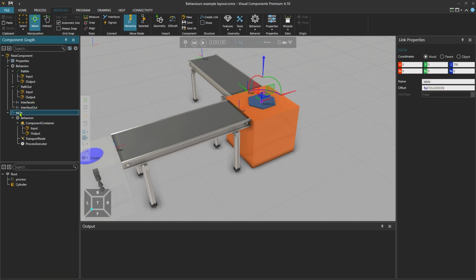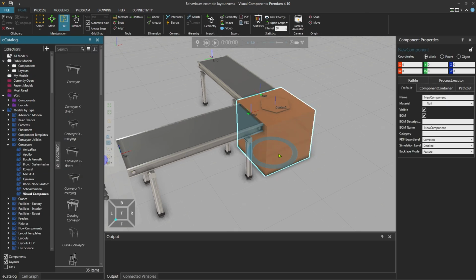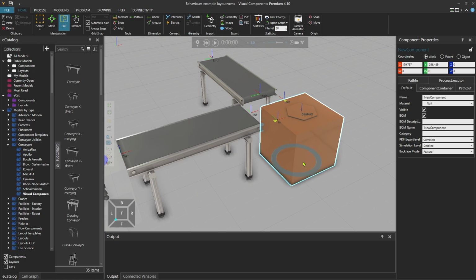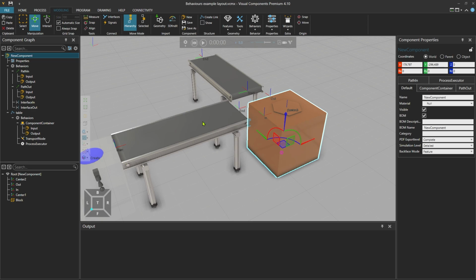the table node, and change the joint type to rotational. However, we can see the selection is grayed out since the component is still connected to other components. So returning to the Home tab, using the PNP tool, we can move the component to disconnect it from the conveyors. And returning to the Modeling tab, some parameters and behaviors cannot be modified while a component is connected.